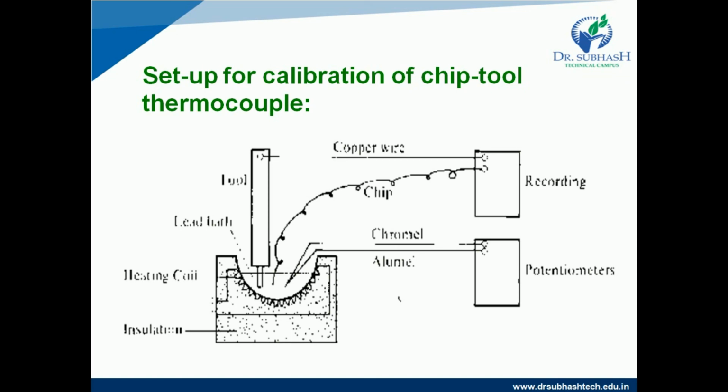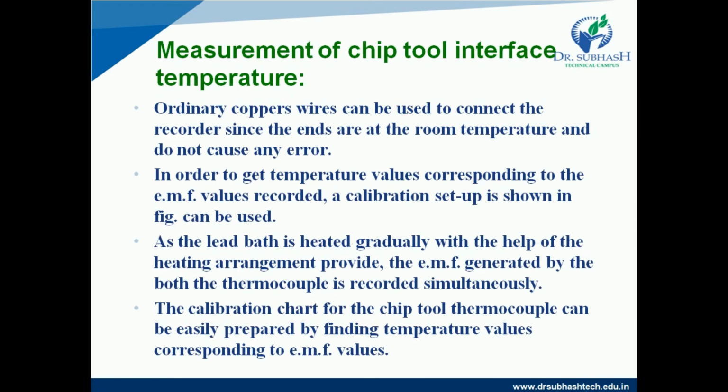As we saw in the previous slide in the figure of the setup for calibration of the chip tool interface thermocouple technique, in order to get the temperature value corresponding to the EMF value recorded, a calibration setup, as shown in the figure, can be used. As the lead bar is heated gradually with the help of the heating arrangement provided, the electromotive force generated by both the thermocouples is recorded simultaneously. So the calibration chart for the chip tool thermocouple can be easily prepared by finding the temperature value corresponding to the electromotive force value. So this is the principle of the thermocouple technique.